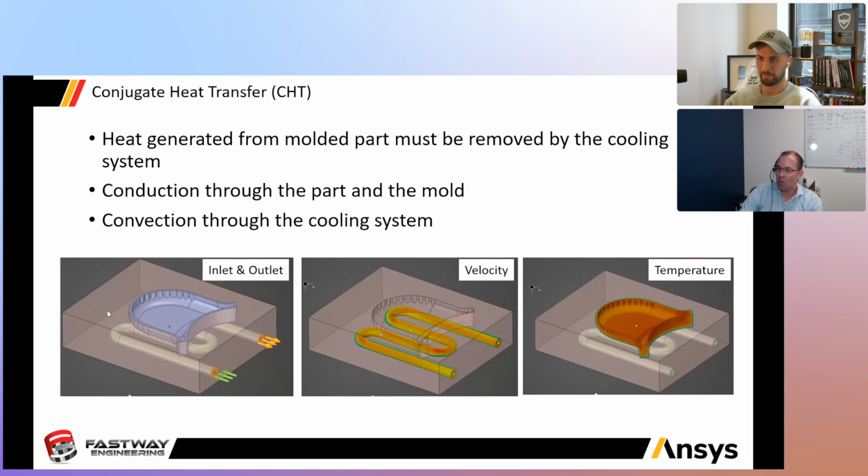Not only that, this is also a transient thing. At time equals 0, I start, I've got my cooling circuit, I've got my temperature, and then I start cooling the mold. So we're not even going to do a transient here. I hope you weren't looking for something super hyper realistic here. But what I've actually done is calculate the equivalent thermal load, wattage, if you will, that would equate to how long it would take to cool this part in like 20 seconds, maybe 10. I can't remember the number I used.